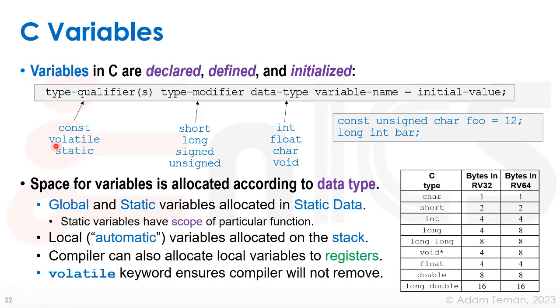So a volatile keyword is something that's not used in general programming very often, but it's used a lot in embedded systems. So we have different types of variables that aren't actually used in a programming way because they point to something that would be an output or something like that of our block. And since it's not used, the compiler would see it and just clean it away, say this is unuseful and not needed, and it will just erase it. If we use the volatile keyword, that means do not remove it to the compiler. So we'll see this volatile keyword showing up very often in embedded C code.